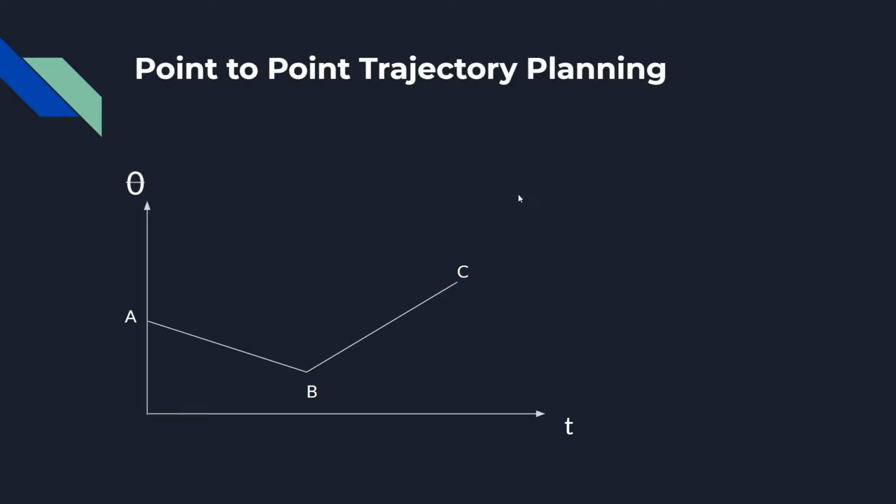And remember that doing this, we don't have any control over the speed at which theta is changing. We don't have control over the speed or the acceleration of the change in position or the change in velocity. So we came up with something called the cubic spline, where we said we're going to change theta according to this equation, which has four different constants, four different variables that we could change according to what we want. So by changing these four variables, we could change what the speed of this joint would be. So we could find out the exact speed of the joint and determine it.